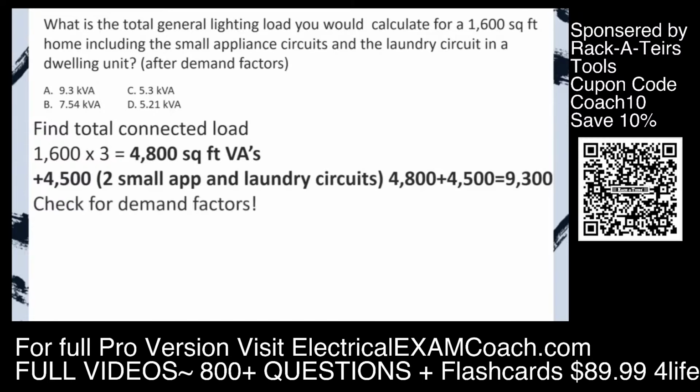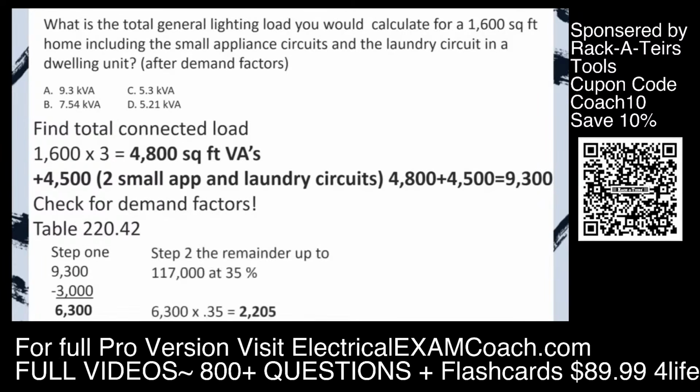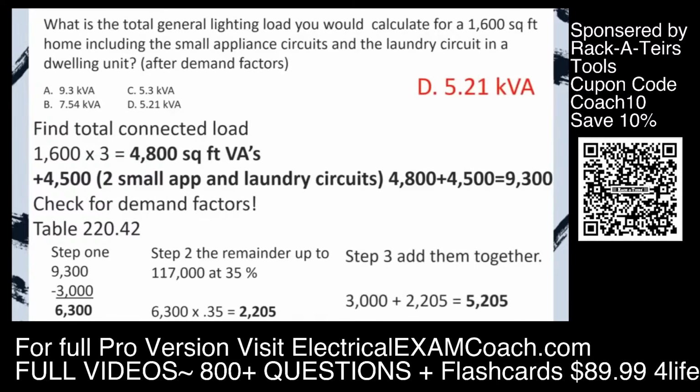Then we take that load and we check for demand factors. We head to table 220.42. We're going to take our first 3,000 at 100%. Then we're going to take that remainder at 35%. Then all we have to do is total the two back together. And we're going to select D.